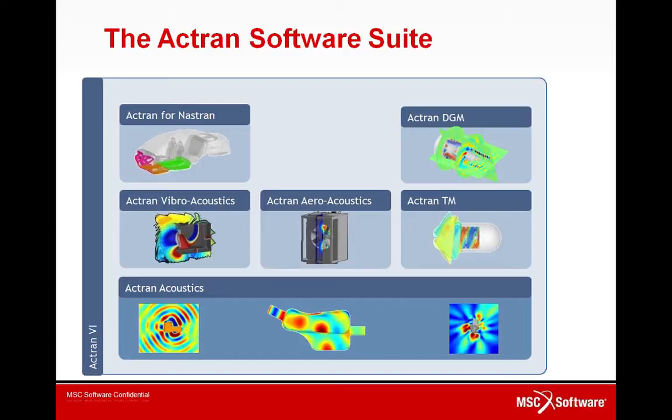And we also have the ability to account for complex phenomena like flows, temperature gradients, or to include any kind of acoustic absorption. Then, if we increase the complexity of the problem by combining the acoustic physics with structural dynamics, we end up solving a fully coupled vibro-acoustic problem, and that's the purpose of the vibro-acoustic module. So this module includes structural finite elements like viscoelastic and composite shells, solids, beams, poroelastic elements, and all the necessary boundary conditions.